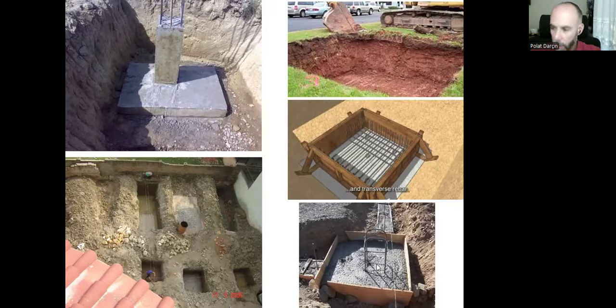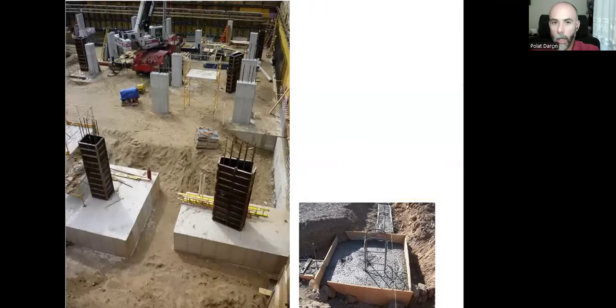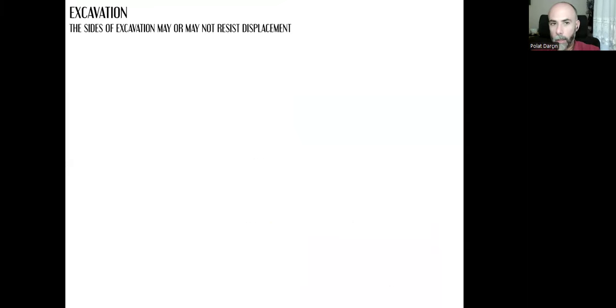Once it sets, we remove the molds and create new molds for the foundation column, put in new reinforcement bars and connect them with the footings. And again, we need dowels to connect it to the superstructure columns, like that. We need these types of forms.